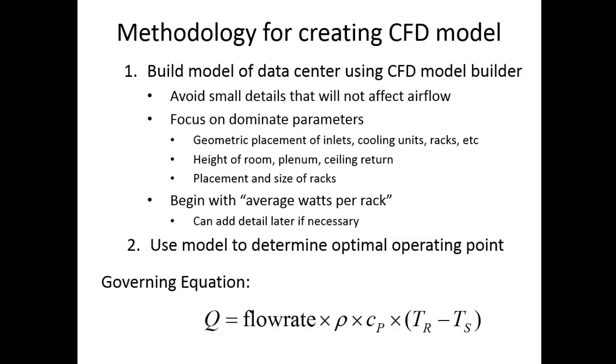You can always dial these models in tight later. It's a great thing about a model. You can increase its fidelity over time if you want. But it's the big things you want to get correct first, like placement of inlets, outlets, where are the racks, placement, number of tiles, percent area open for the tiles, height of the room, general big things.